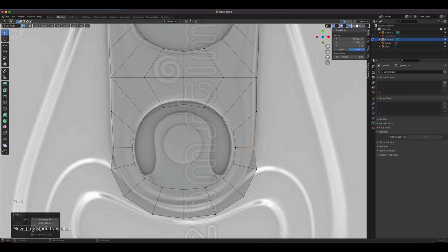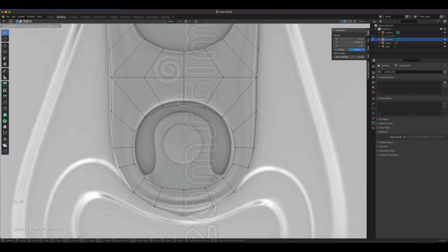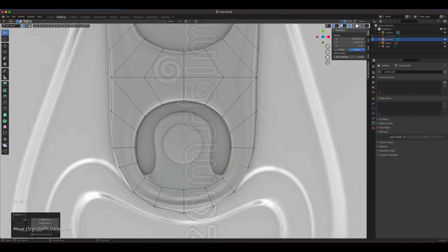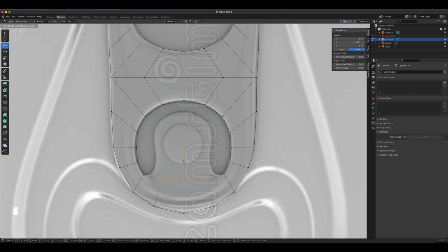Again, I'm trying to straighten my topology right here so it's not stretched. So it's very important that you learn what you need to do with topology at the beginning, so you don't have to struggle with that later on, because when you're just starting, and we all started this way, we are attracted to high polygon count. So we always do a lot of high polygon, and it just makes it harder to do some modeling when it's high poly like that.